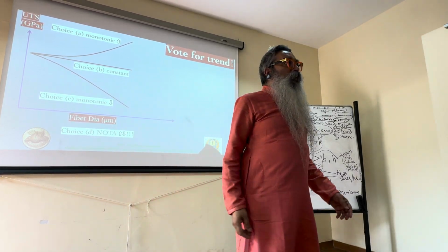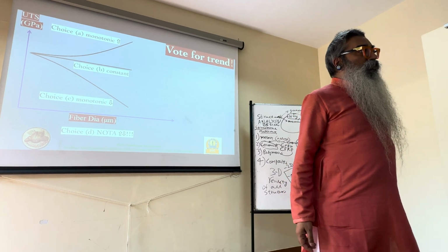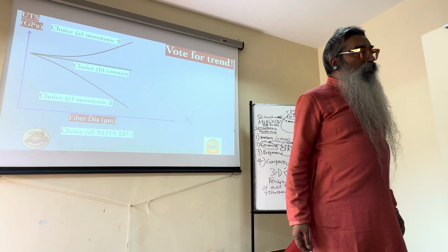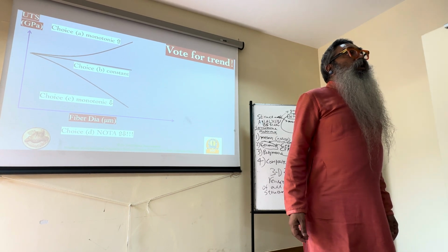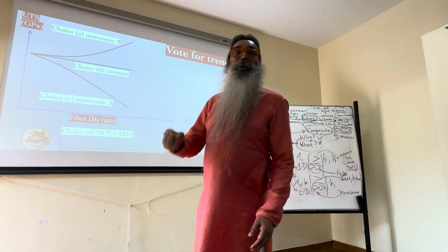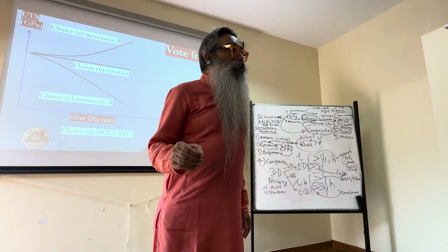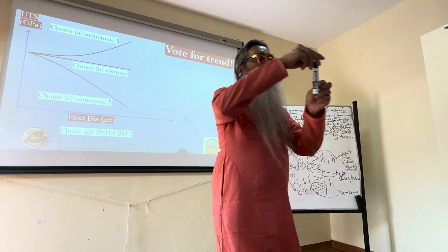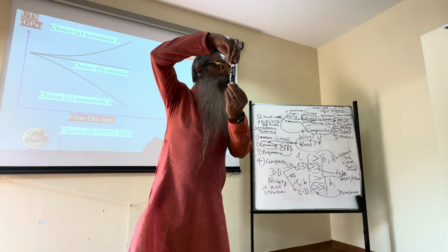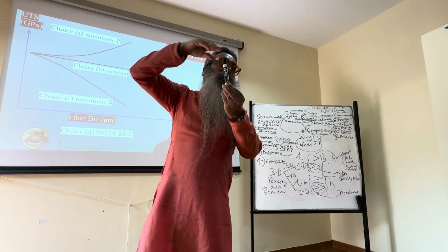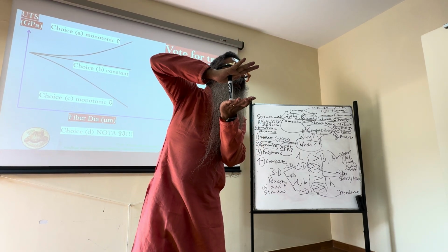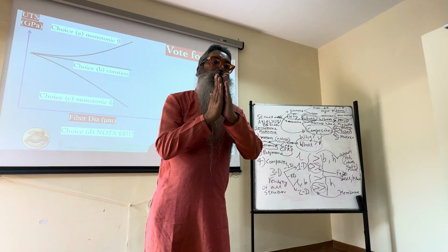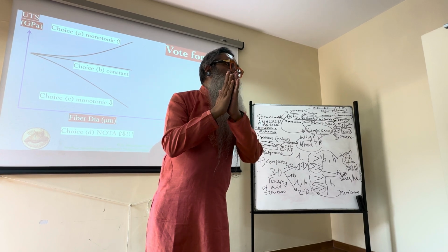Ultimate tensile strength for each material is very specific, it's fixed, but tensile strength is a different value, right? No, see, ultimate tensile strength is a particular kind of strength. There are many strengths like that. If this is the specimen that I was trying to pull and get the stress at which it fails, I get UTS. Instead of pulling, if I were pushing it in, I would get UCS, ultimate compressive strength. Similarly, if I were to shear this, I will get the ultimate shear strength, right?